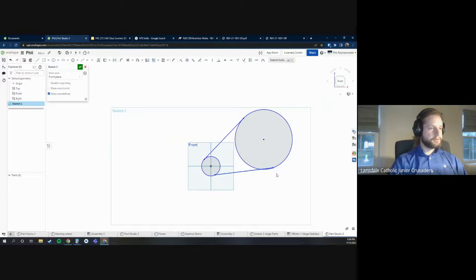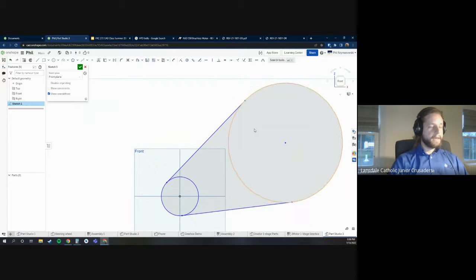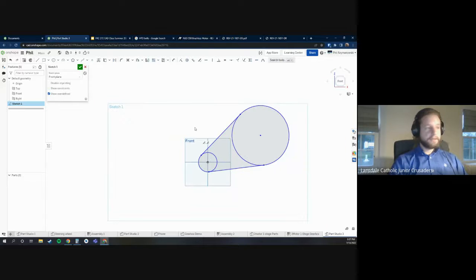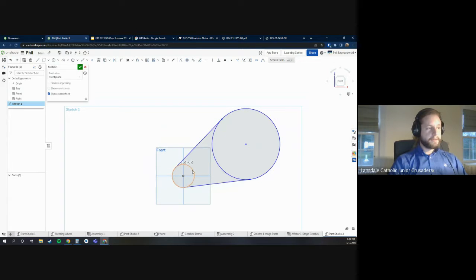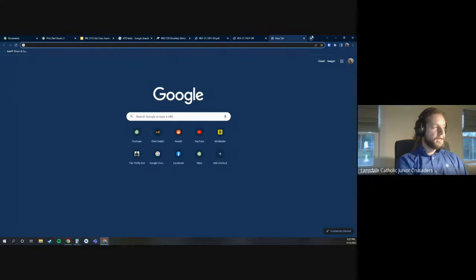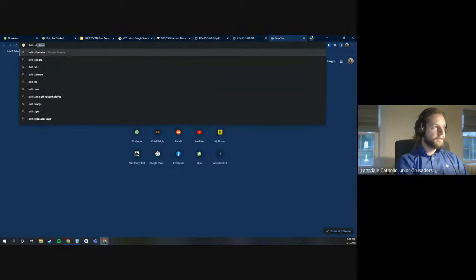That'll just show you. It's not really useful in terms of designing it, but it is useful in terms of showing you where the belt is going to run. And the idea of pitch diameter with belts is exactly the same, except the belt pulley pitch diameter calculations are just a little bit different. And what I usually do to do this is I go to a belt calculator.